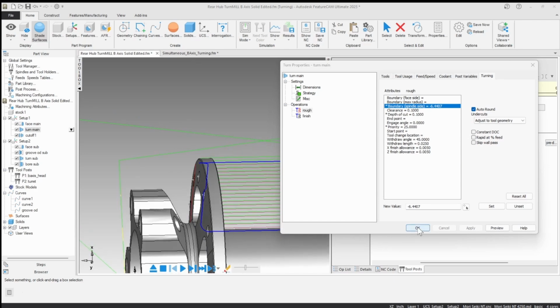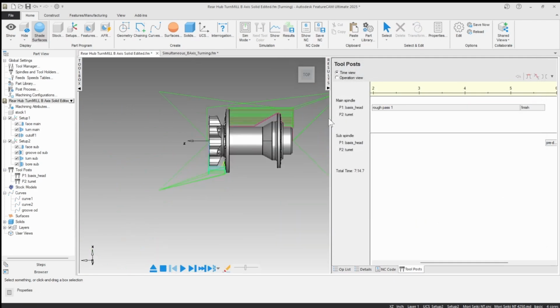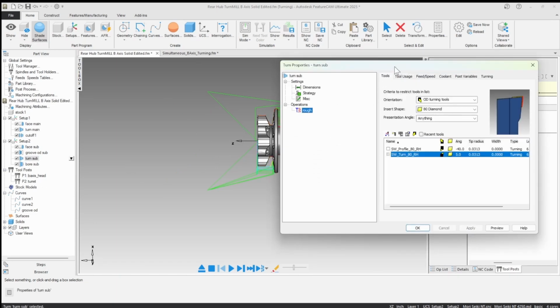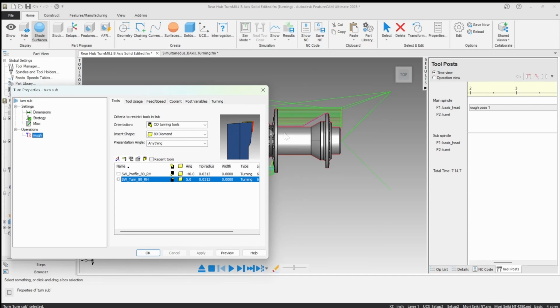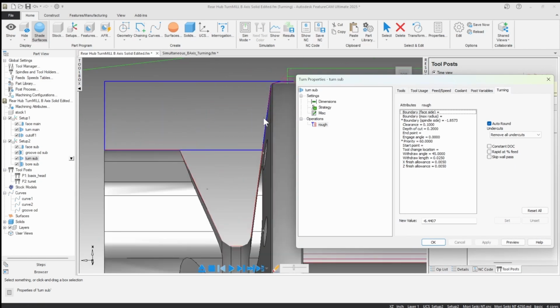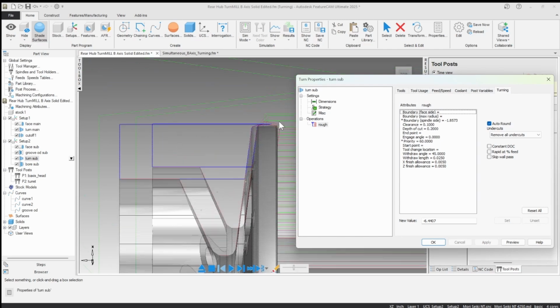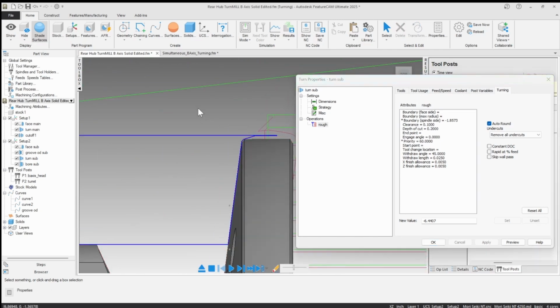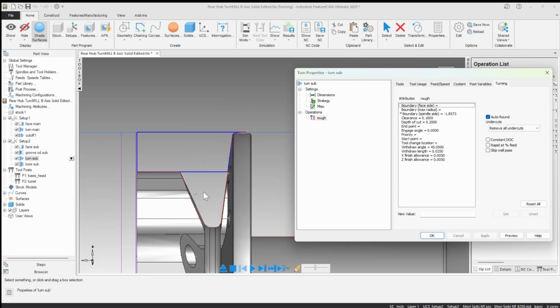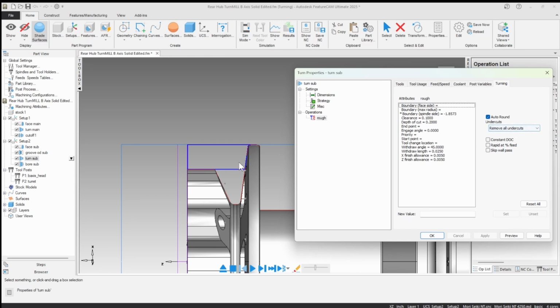So that works. And then on the sub spindle, I did the same thing. And I have just a rough pass. Now it shows the turret in the lower turret. It's upside down because I moved it, so it just automatically does that. Here's the machining area that it's doing, because remember I have a groove feature that's taking care of this. So I'm just basically blending this radius. Okay, so I got it set there, and that's where we want to end up basically. And so we're staying out, so I do have the undercuts removed here, and then just set a boundary on the spindle side.